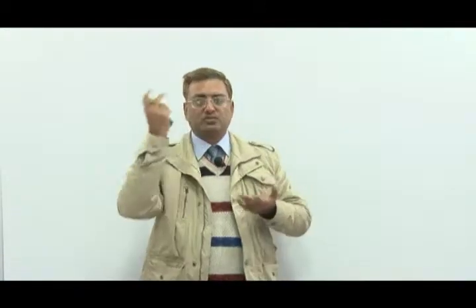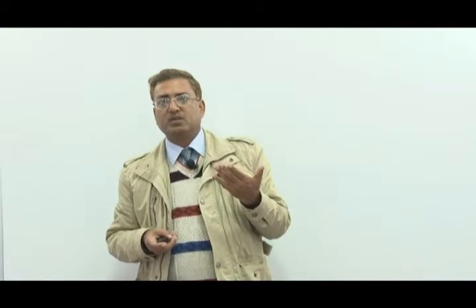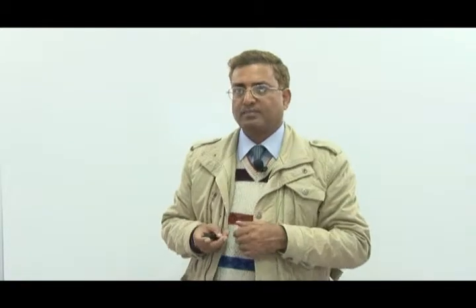So for the axisymmetric case, if you choose a 3 nodal ring element, all around, one can specify the r and u like this. So these are the elements, 1 2 3 and 1 2 3 the variation. So this shows the 6 nodal element, which we call a ring element. On the other hand, there is a 4 nodal ring element also, as one can see.